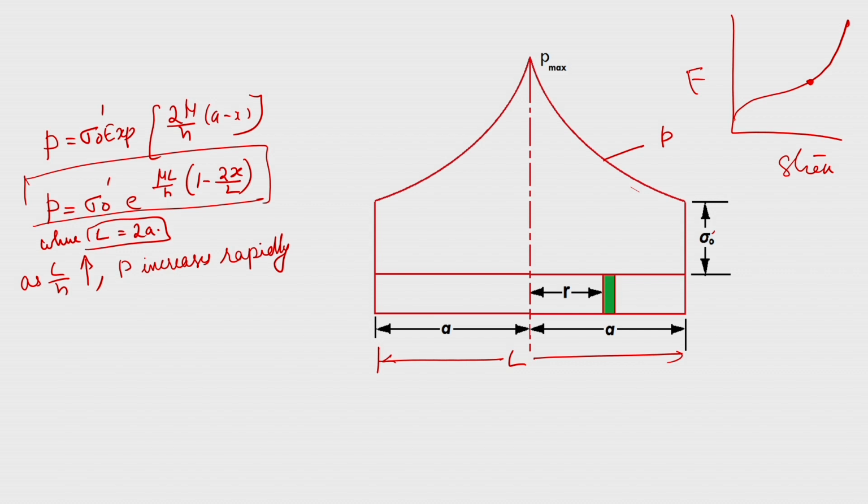With the thickness of the flash decreasing, the stresses necessary for the deformation will be very high. That is why it is much safer, because for the metal to deform and form the flash and then fall into the flash gutter, the pressure will be higher.